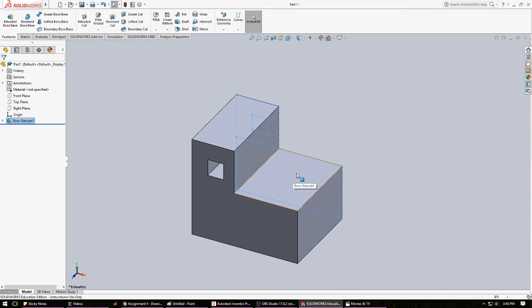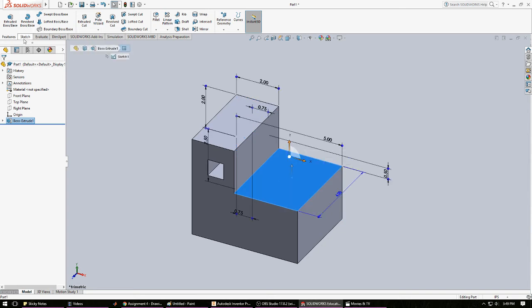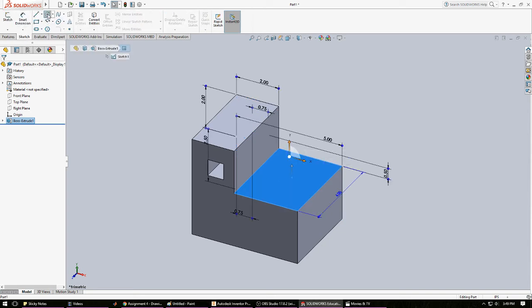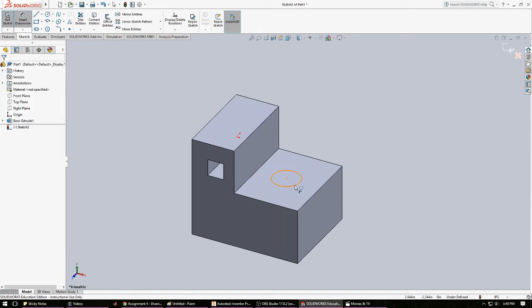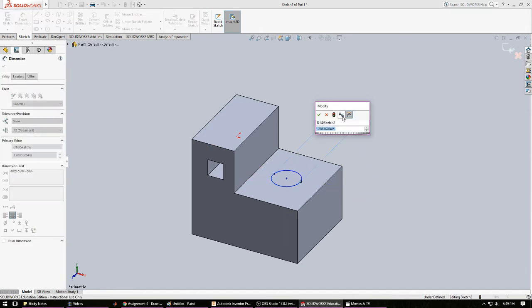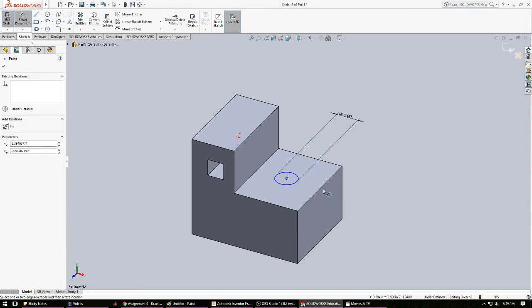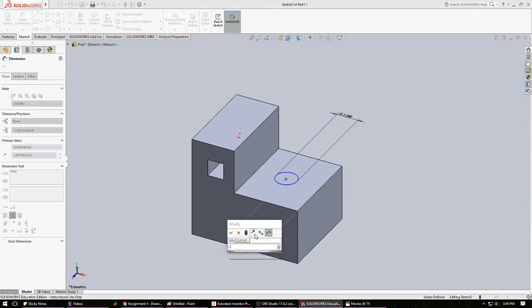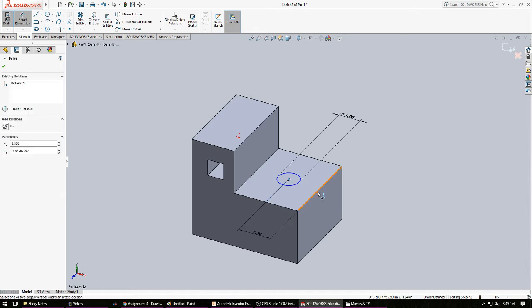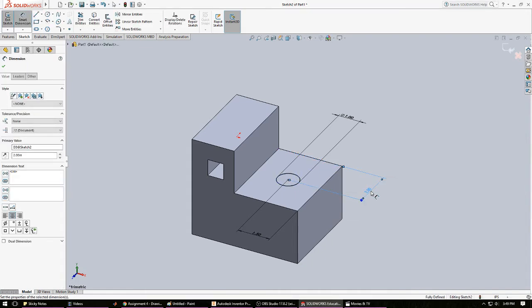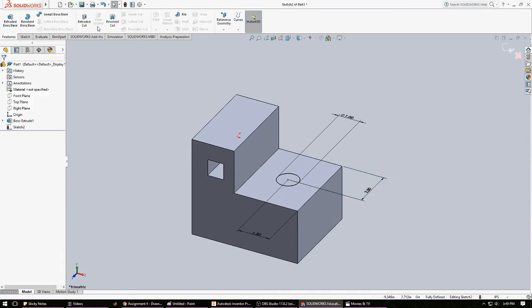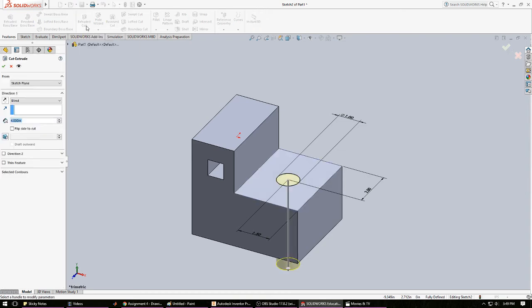And then I think what I'm going to do is select this surface, and then sketch a circle on top of this surface. It seems sideways because I'm not bothering to show the top face. So if that bothers you, then you can change it to the top view. This isn't stuff I anticipate, like, whoops. Okay, awesome. And then we will do an extruded cut.